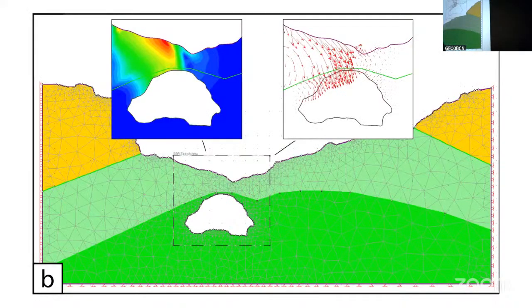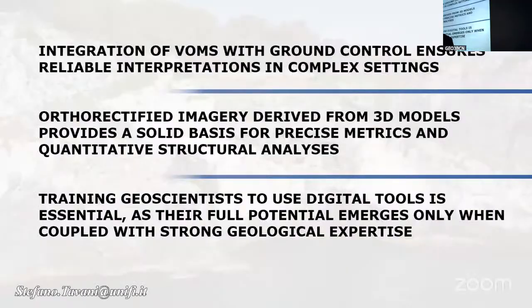And well, of course, we have done some kind of finite element modeling in order to assess the stability of the vault. Despite this red material, this red color here, the vault is quite stable. The basic problem is that this material is highly erodible, so the recommendation is to build a barrier here to prohibit working on this very thin bridge. And well, that's all. Just a few considerations.